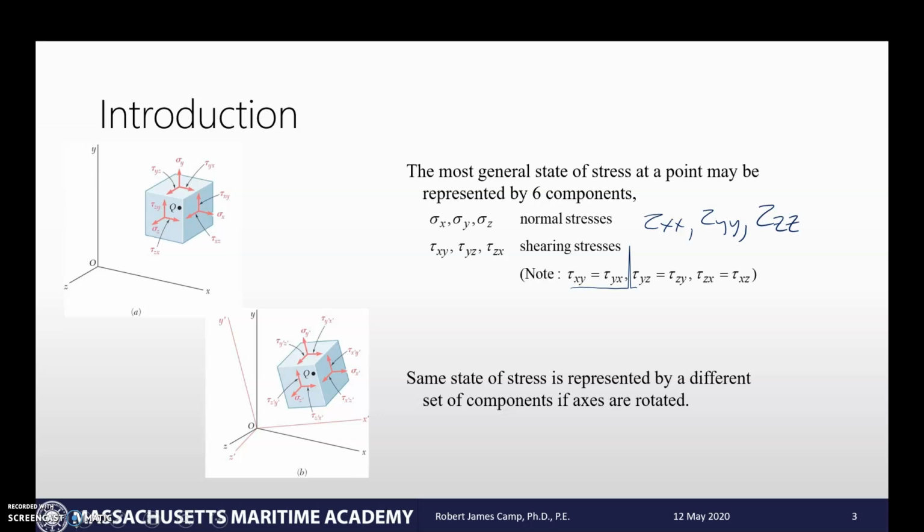In torsion, you are going to fail along the normal stress axis, especially for a brittle material. And that normal stress in torsion is where you get that corkscrewing break at 45 degrees. Well, how do you figure out what the normal stress is at 45 degrees? We can rotate the entire stress cube and remap all the stresses on a different axis. We haven't changed the state of stress, but what we have done is changed where we're looking at them.